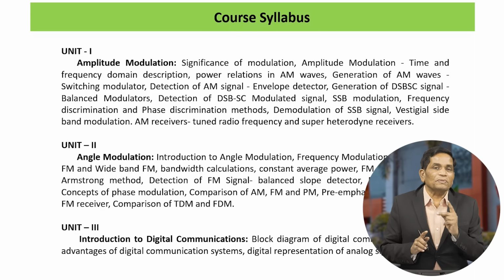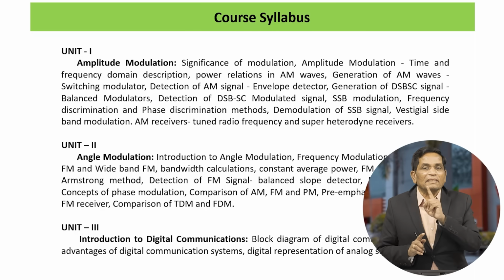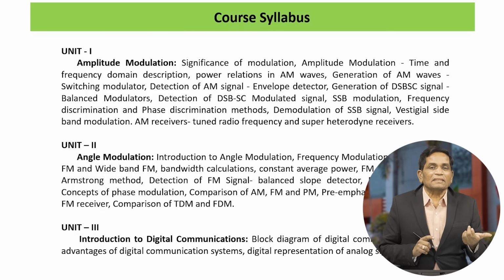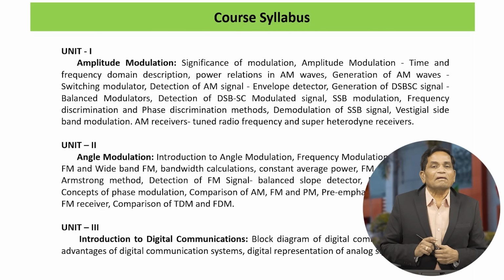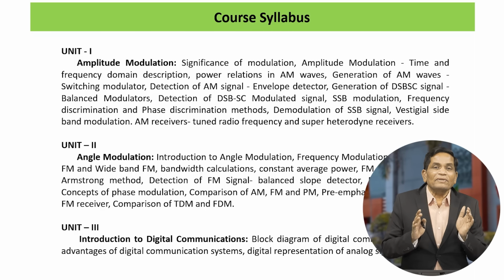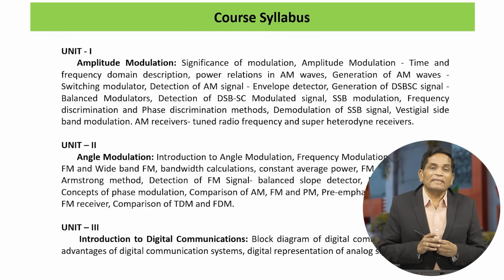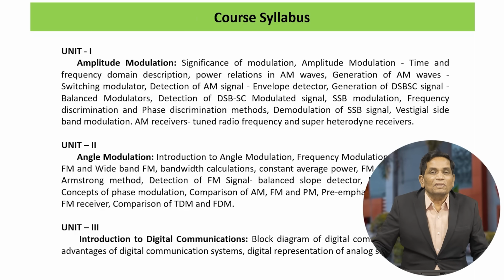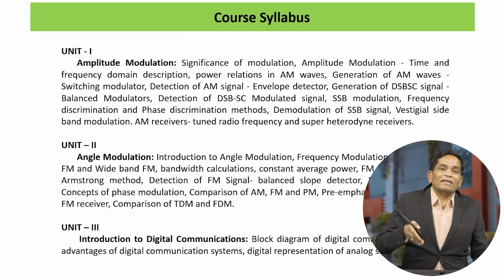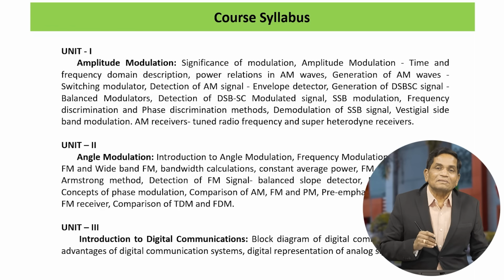Signals are classified into two types: deterministic signals and random signals. Deterministic signal means like a sinusoidal signal, step signal, ramp signal. All these are called as deterministic signals, and we can represent them mathematically. We can represent mathematically, but it is impossible to represent a random signal mathematically. If we are not in a position to represent it mathematically, how to do the analysis? So that is why the probability concepts are required to analyze the random signal.